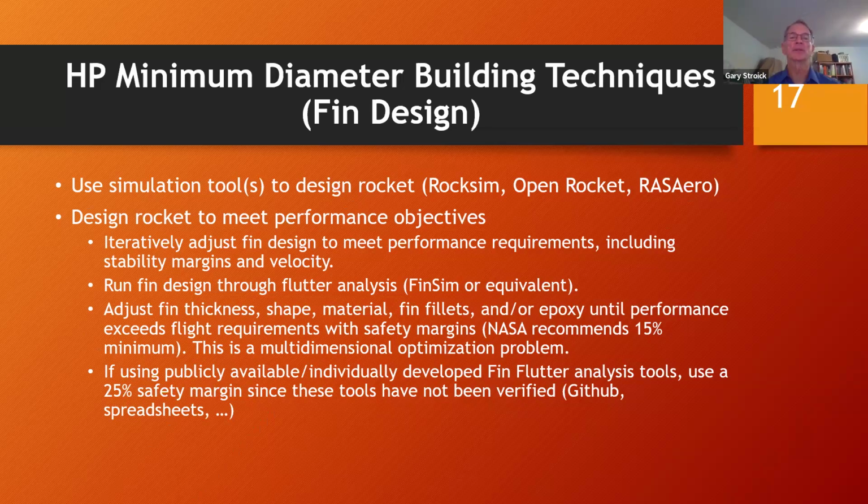During the design process, you'll want to go through the process as you would when designing your model rocket or high power rocket, but you'll want to iteratively adjust the fin design to meet the performance requirements. One of the things you need to look at, in addition to altitude, your maximum altitude, would be the stability margins throughout the entire flight and the velocity. You want that data.